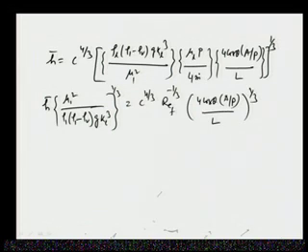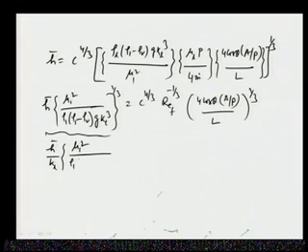So, this is the rearrangement, and the left hand side can be written as h bar by k L. If I take the root of this, it comes out to be k L. So, h bar k L into mu L square by rho L into (rho L minus rho V) into g, whole to the power 1/3. So, this is h x by k, some characteristic length. This thing is basically your Nusselt number, and that is equal to C to the power, the right hand side.